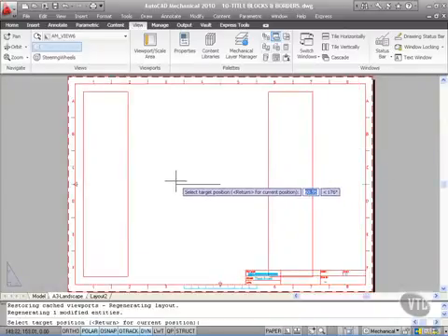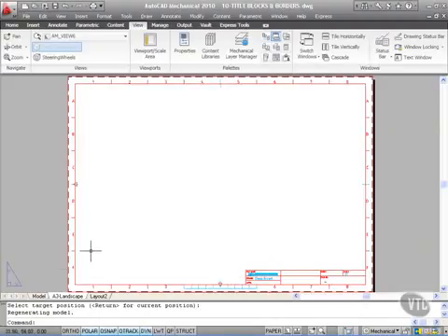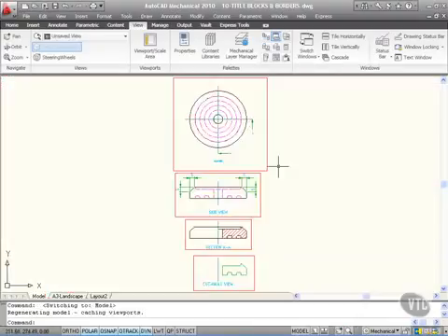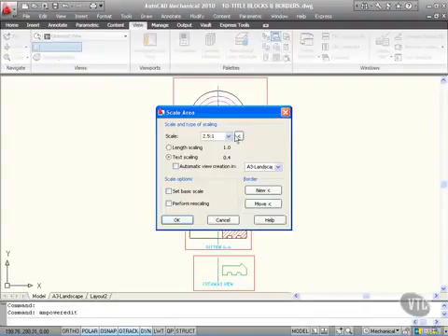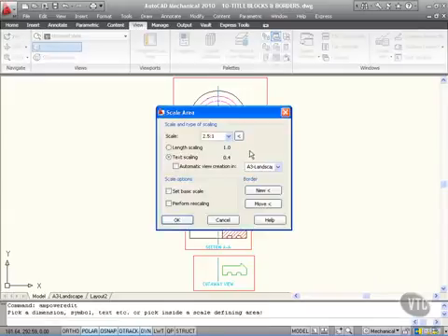It's quite big, you'll notice. Look, if I drop that in there, it's going in at twice its normal size. In fact, 2.5 its normal size there. So what I'm going to do there is I'm going to cancel that. I don't want that to go across. I go back to model here, and what I'll do now is I'll edit this one. So I'll double click on the scale area and say that I want to take that back to the actual 1:1 size that it originally was. Now I can just hit escape there or click inside there and it allows me to edit it.